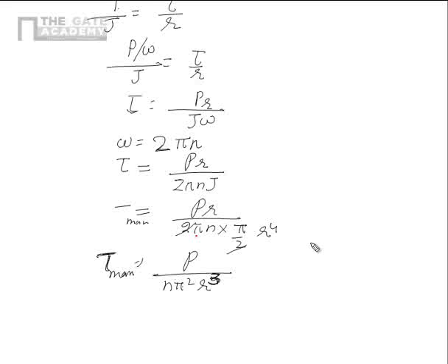So this is about the torsion. Torsion is a very important phenomenon because torsion helps transmit powers. Most of the power transmission machinery and even the power generation machinery, like turbines, which have long shafts of the coil or magnet rotating inside a coil or magnet to produce electricity, are all loaded by torsion, and torsion is a very important loading condition. And this tau max formula for power transmission is a very important formula to remember.